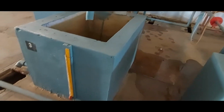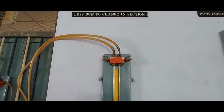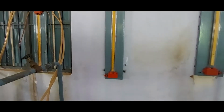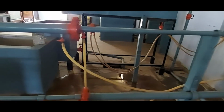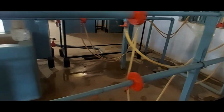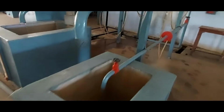Let's move on to loss due to sudden change in section. From this experiment we shall determine the head losses across sudden enlargement and sudden contraction. Now we are able to see the sudden enlargement pipe. Below that we have sudden contraction pipes. These losses are considered minor losses because the pressure drop is small compared to major or frictional head losses.